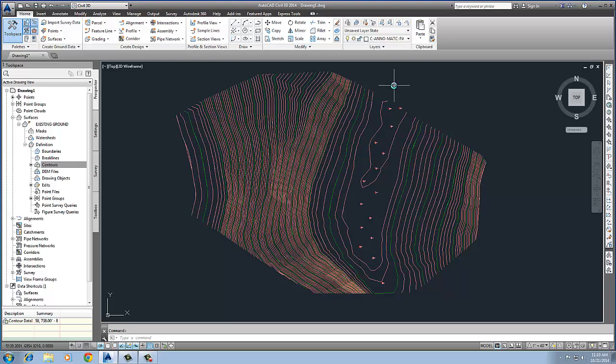So the next thing we're going to do now that we have a good surface, and remember we could go out and look at some of the visualization on that, but we're going to go ahead and generate our tangent data, and you have a Lab 6.8 schematic layout sheet. Let's go look at that. If you notice, we're starting at a point, northing and easting, and we're going to travel along an alignment defining 3 tangents, and then ultimately we're going to come back in and put some curve data in there.